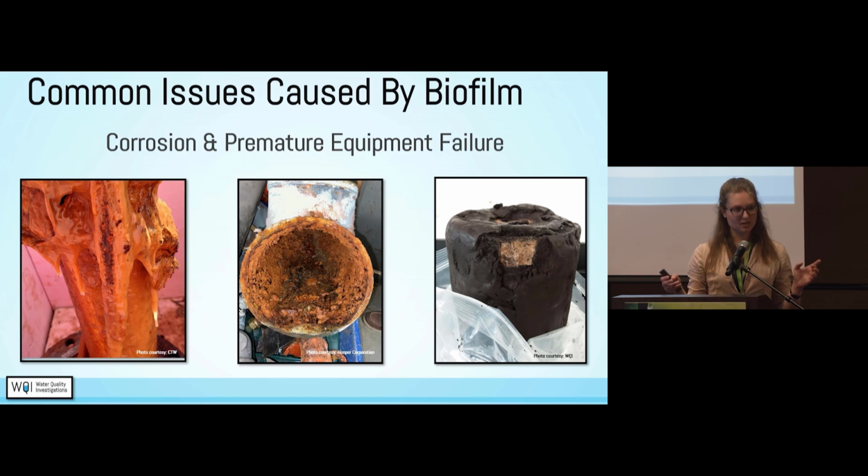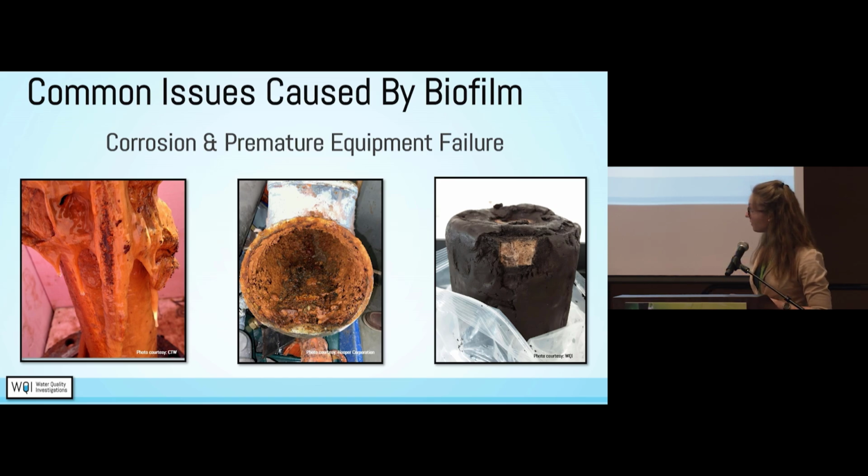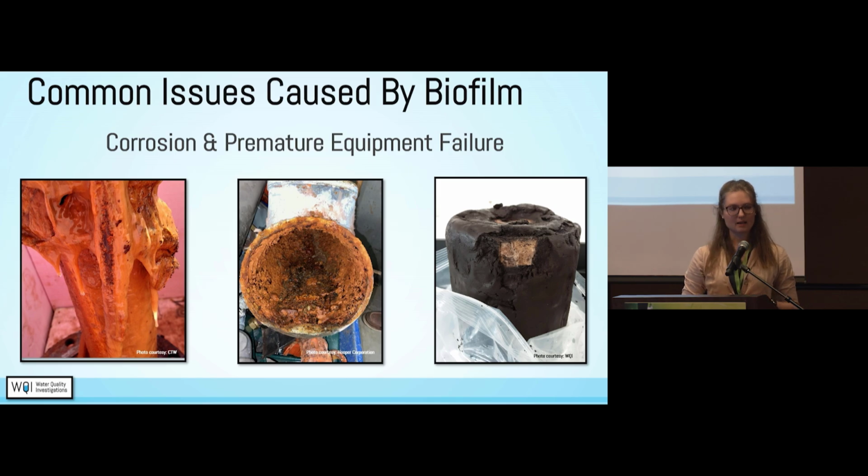Now, here are some really extreme issues. These are actually all examples from Wisconsin. We do work all around the United States, but I wanted to bring it home and show that this is in our communities and in our homes all over the place. So on the far left, you might be wondering what that is. That's actually a well pump from a municipality, and the municipality had lost capacity to pump water. When they pulled the pump, they thought they were just going to replace it. They found it was actually completely covered with this slimy biofilm material, and that it basically shut off its capacity to pump.